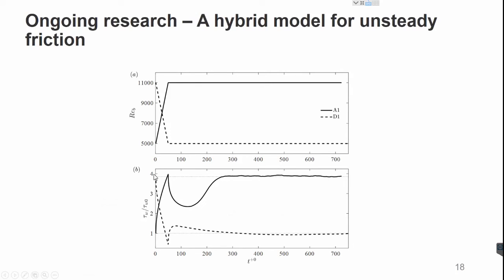And from intuition, in the decelerating case, we would expect, or at least I would expect, to see a mirrored behavior. But we can see that decelerating flows do not respond in the same fashion as the accelerating case. So we can see that there are some differences. And also the core relaxation stage in a decelerating flow seems to take longer periods of time.